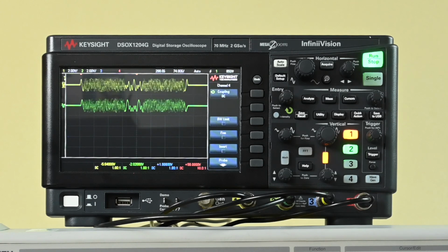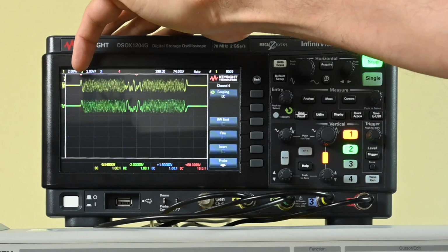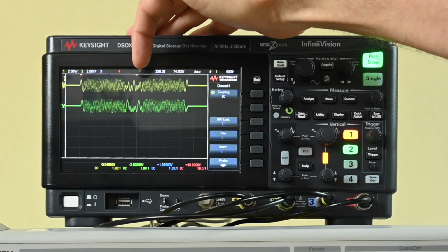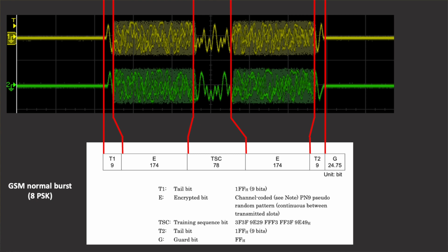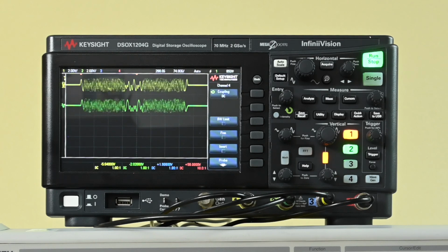This is very interesting because what we actually see is precisely how a GSM signal burst is being defined. It starts always with a fixed type of pattern and ends with a fixed type of pattern. And in the middle, we basically have a training sequence. That training sequence basically allows the GSM receiver to see some known type of information, and from that it can infer what the characteristics of the radio channel are, and it can adapt to it, including the thresholds it's using. So it's actually a very advanced system, and back in its days that was one of the things that made GSM a more capable mobile telecom system than some of the competing standards like DAMPS and the PDC standard from Japan.